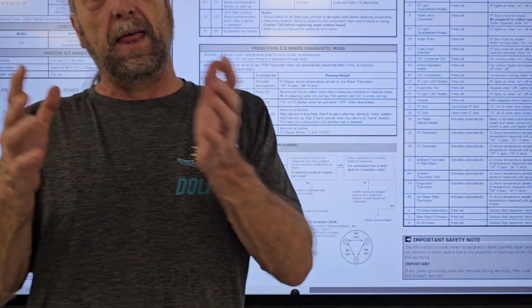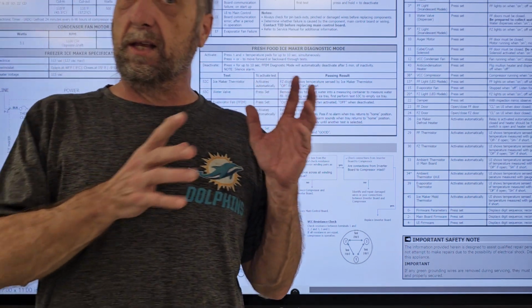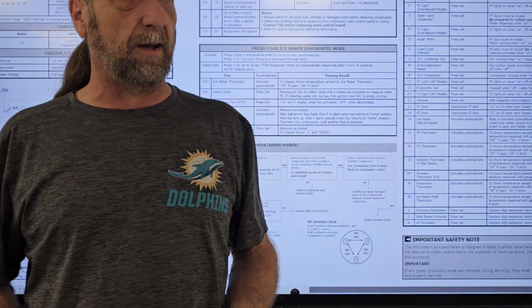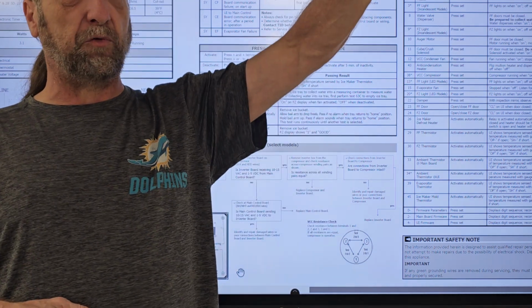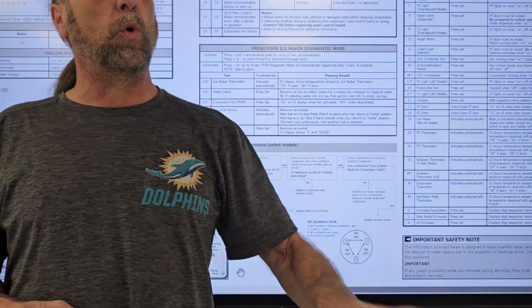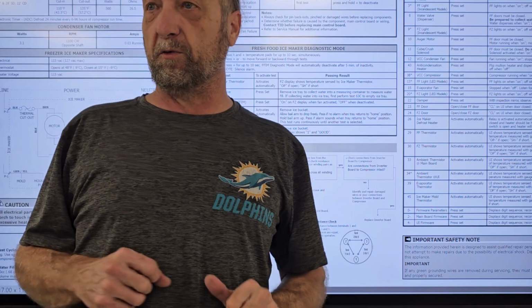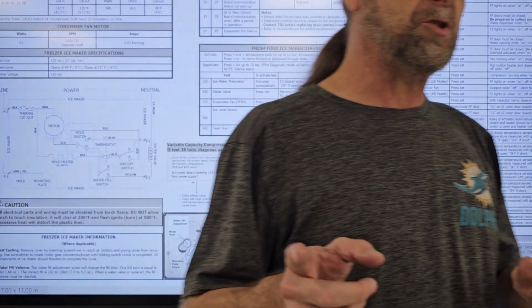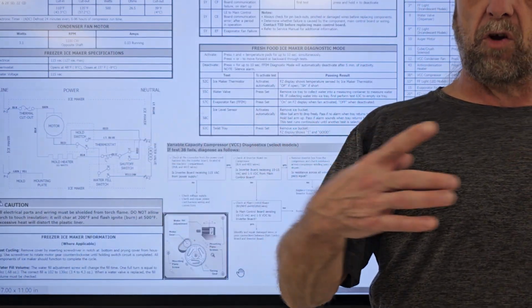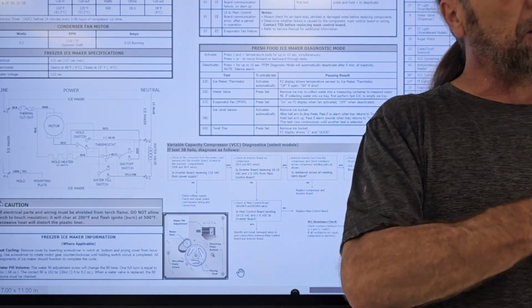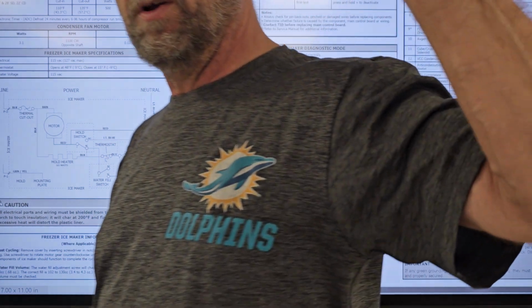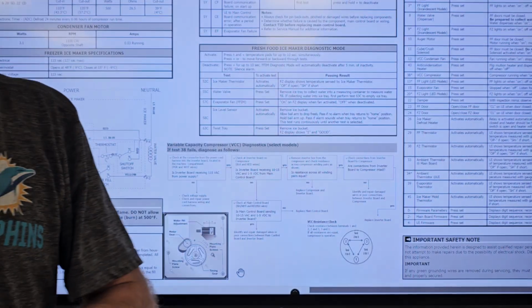And they decided, well, we're not going to redesign the entire fridge for this little flex tray ice maker. So what we're going to do is the flex tray is up in the freezer in its own compartment. We're going to pre-wire the refrigerator and design it so that if the customer wants, they can install a Crescent cube ice maker in the freezer section that runs independently of that ice maker. So it'll be in a freezer just like the old Whirlpool ones.